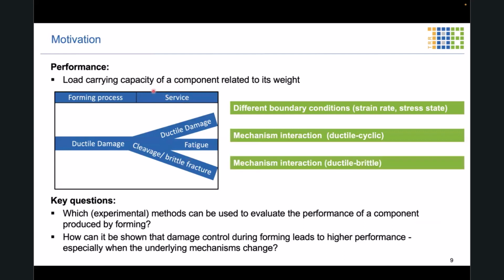And finally, a mechanism interaction between ductile damage during forming and cleavage fracture during the service behavior of the component, usually triggered because the temperatures that the component experiences are relatively cold. Now, having this in mind, we can also argue that the performance then is the load carrying capacity of a component in the critical load case related to the weight of the component.